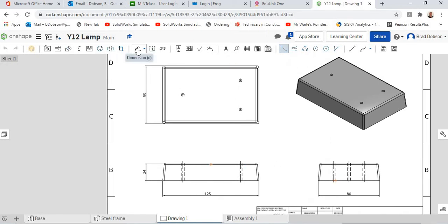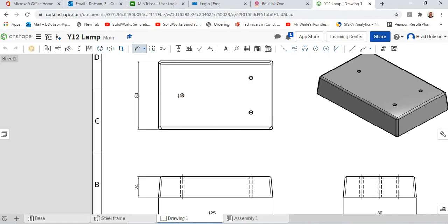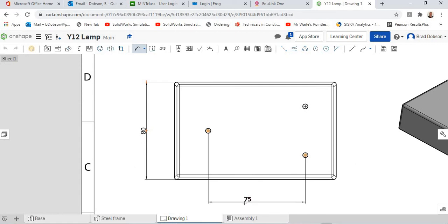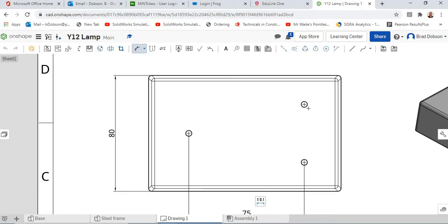So I'm then just going to go back to basic dimensioning. So I'm going to put dimensions. Again, I need to zoom in. So I want the very centre of the circle, centre of that, and again I want this dimension. It's good practice to always have your dimensions where possible off your drawing, so it's not making a mess of the actual drawing itself. I'm going to do the next one on this one over here.